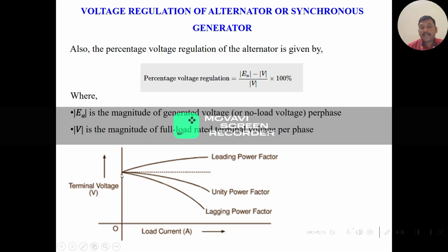And when you connect the capacitive load, we know that the resultant flux phi r increases with an increase in the armature current. You can see that when you connect the capacitive load across the output terminals of the alternator, the terminal voltage of the alternator is greater than the rated voltage. This is due to the magnetizing effect in the alternator.